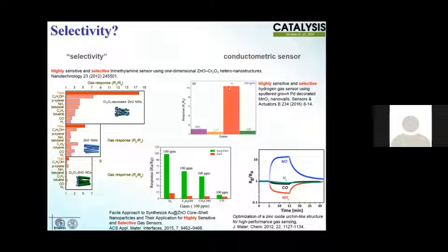Now, I'm not questioning the fact that the numbers are small. I am questioning the fact that they are numbers. I mean, one pure number cannot give selectivity. I think that's quite reasonable. Indeed, the only selectivity that such a device, a chemoresistor, has is this one, basically distinguishing, with a resistance that increases or decreases, the two big families of oxidizing or reducing gases. Among these big families, they are not able to distinguish anything, so they have no selectivity at all.